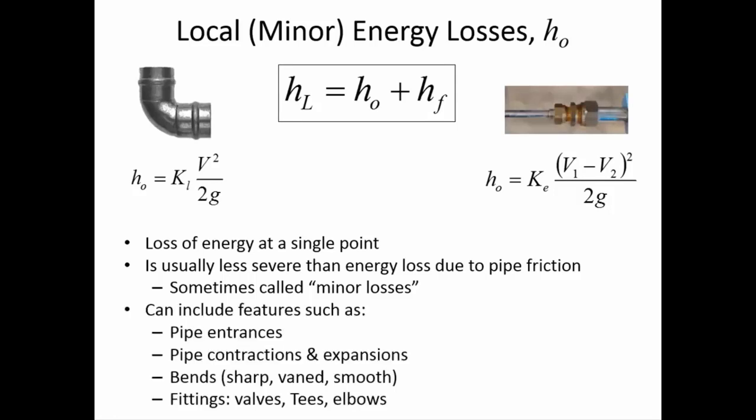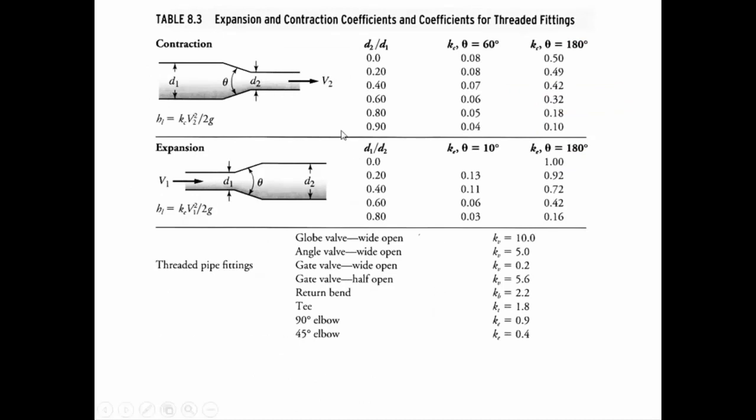And then the other thing that you noticed here, in this one, it's saying 1. And so if you have the pipe exiting into a tank, then what that is implying is that in that exit, you're losing 1 times the velocity head. And so that means all of the velocity, all of the energy that's in velocity, when the water discharges into the tank, that energy is just instantly lost.